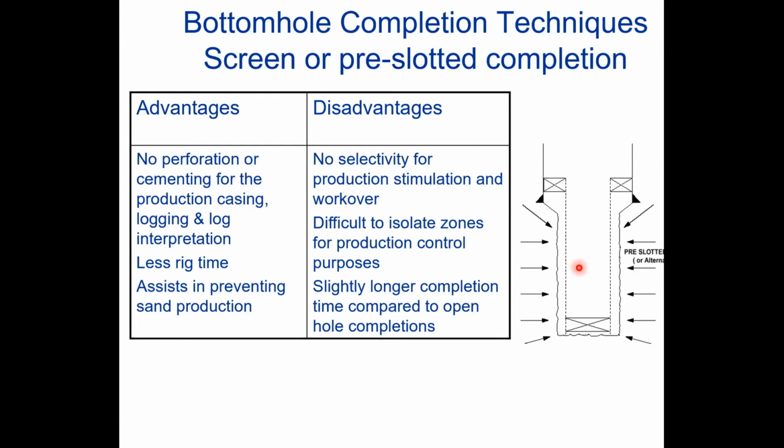There are two major options to prevent sand movement. One is to inject sand, a special size sand, behind the screen to prevent sand movement.